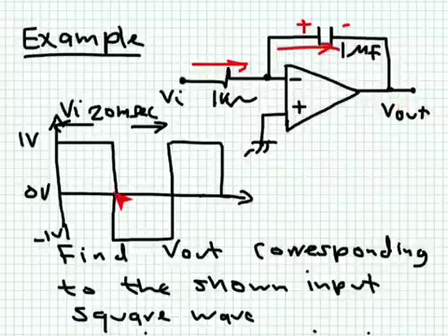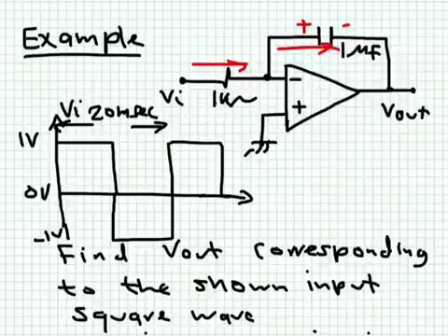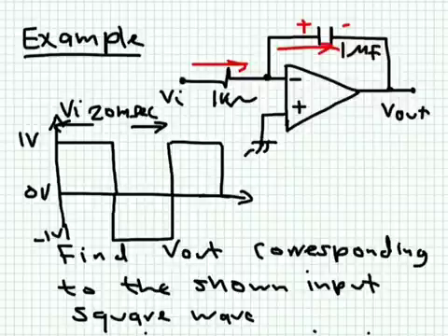Now, if you apply a negative voltage like this one, the current will reverse direction. Then the current flowing from the capacitor will reverse direction. Then the capacitor is actually discharging, okay? So it will start to discharge back to its original value. The important part to remember is that the capacitor is charging under constant current.